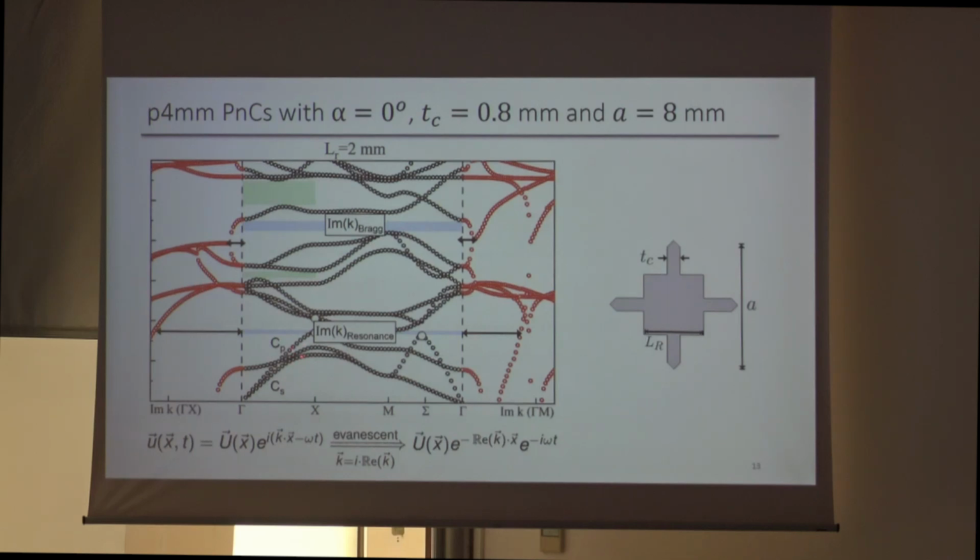This band is the shear wave, or transverse wave, band, and this is the CS velocity, which is the square root of the shear modulus over the density of your solid, and CP is the square root of the Young's modulus over the density. So these are the slopes, and these are the allowed, propagating modes.